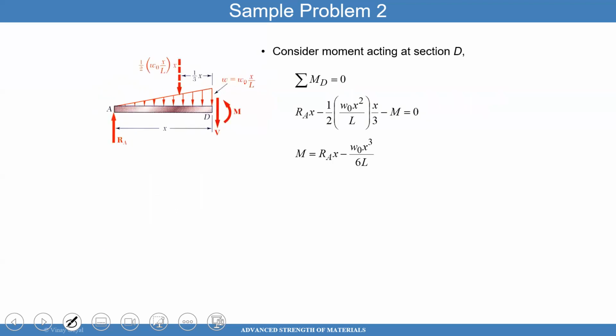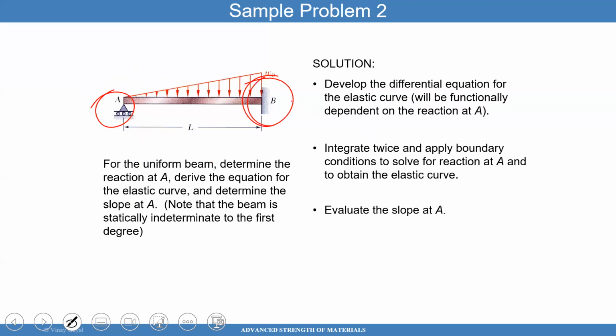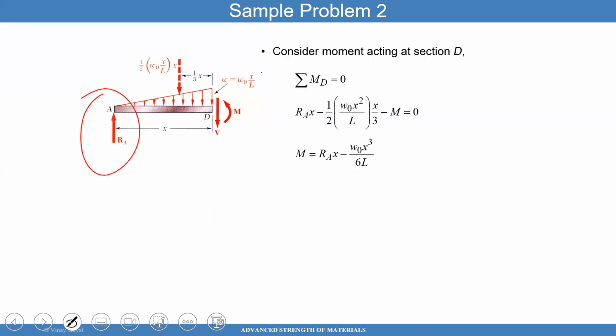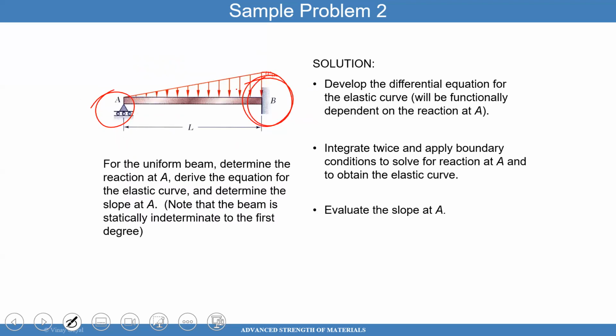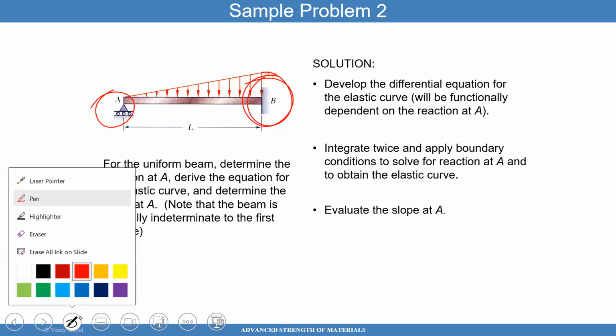The left-hand side I removed and replaced with a reaction force RA. The right-hand side was clamped, but because I removed the clamp condition, that means I must have a shear force V and a moment M. So those two will show up. Now, I actually didn't do that the way I'm saying it, so I want to be careful about my words there.